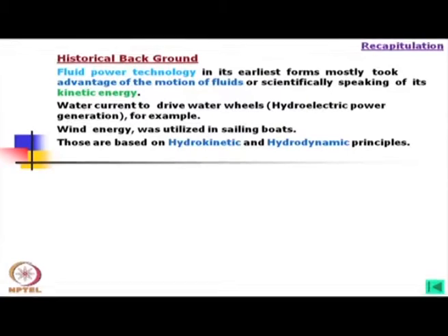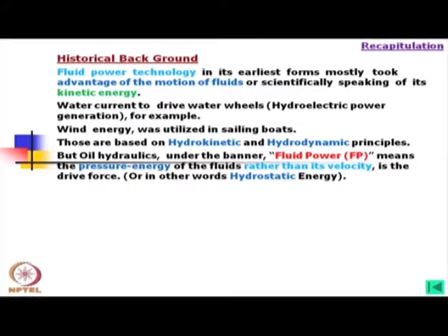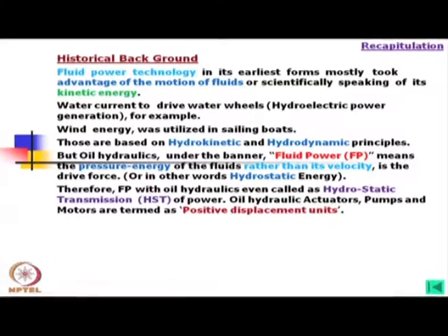We call them also hydraulic machines, but fluid power is really different from those hydrokinetic or hydrodynamic principles. Here what we need is the hydrostatic behavior of the fluids. Hydraulics under the banner of fluid power means the pressure energy of the fluid rather than its velocity is the drive force, or in other words, hydrostatic energy.